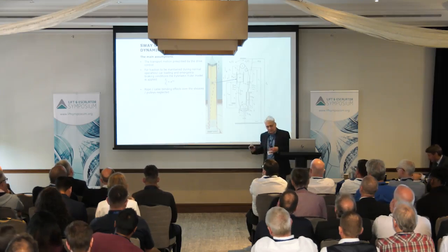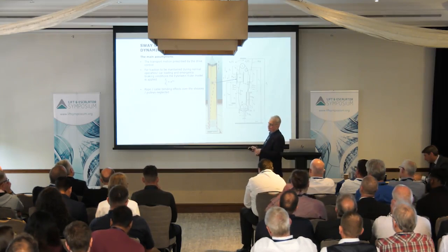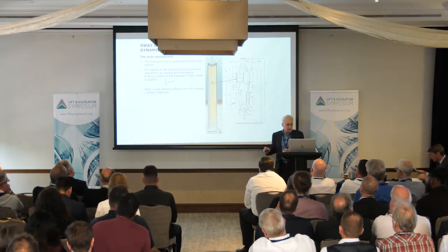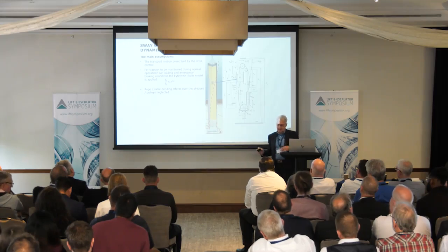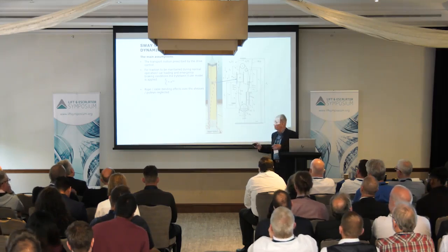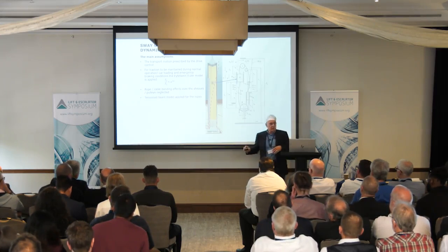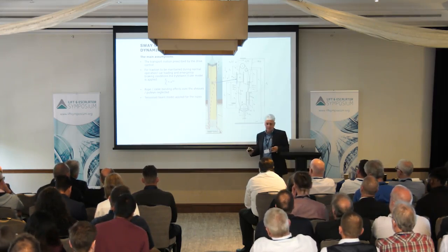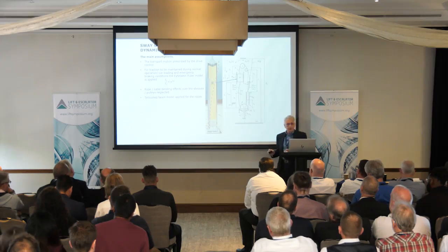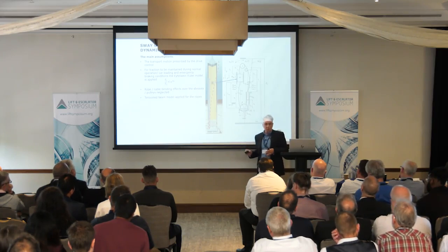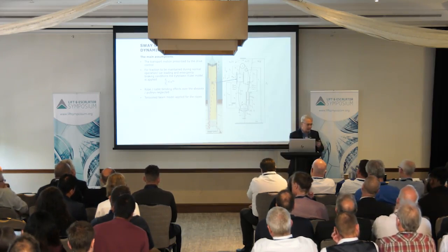In the model, we need to apply some simplifications. In this case, the rope bending over the sheave will be neglected in the analysis. Now, we have a tension in the ropes. We need to assume, again for simplicity, that the tension is equal in all ropes, which is not exactly the case, as Tim mentioned.